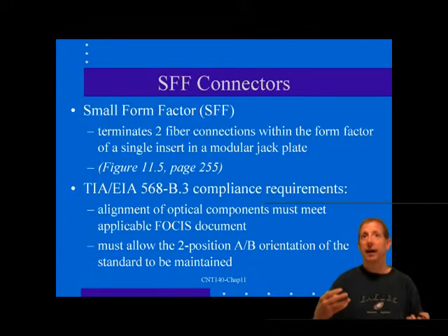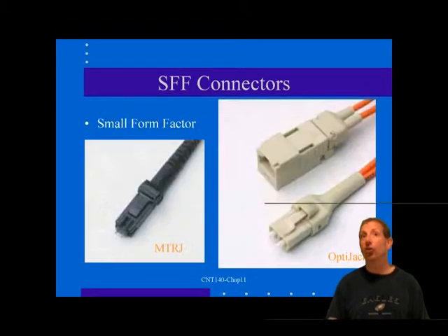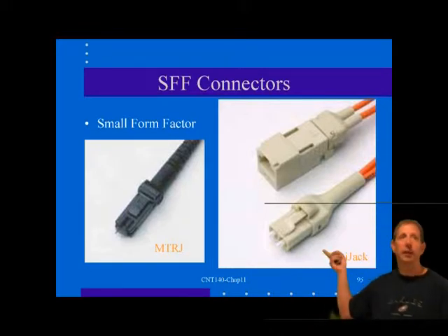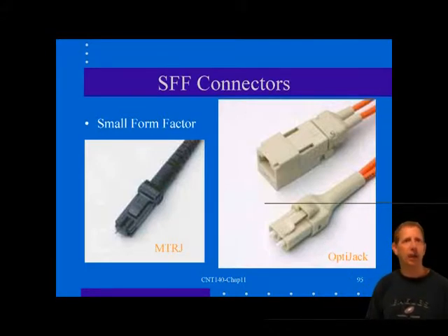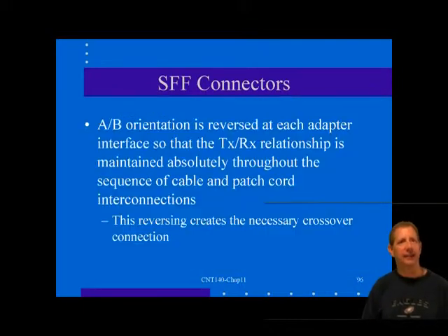The TIA 568C optical fiber cable and component standard drops the requirement for a specific connector on the basis that this will encourage innovation and that the market will determine usage. The connector can be of any configuration that meets certain requirements and does not have to be exactly like the copper modular RJ type connector. The figure behind me shows some of the more popular SFF connector types in contrast to the conventional 568SC connector.